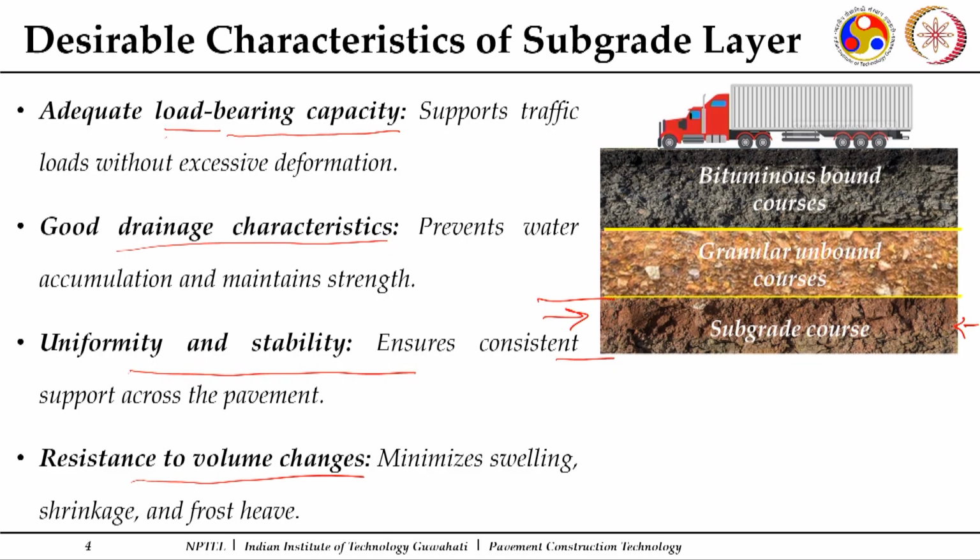So, with water holding, when the water moves out and when the water comes in, we look at how the volume changes, because if there is some volume change in this subgrade layer, that will affect the layers above. If there is some swelling, it will uplift, it will put an upward pressure and try to lift the above layers which are over the subgrade. So, that kind of characteristics is not desired from a subgrade.